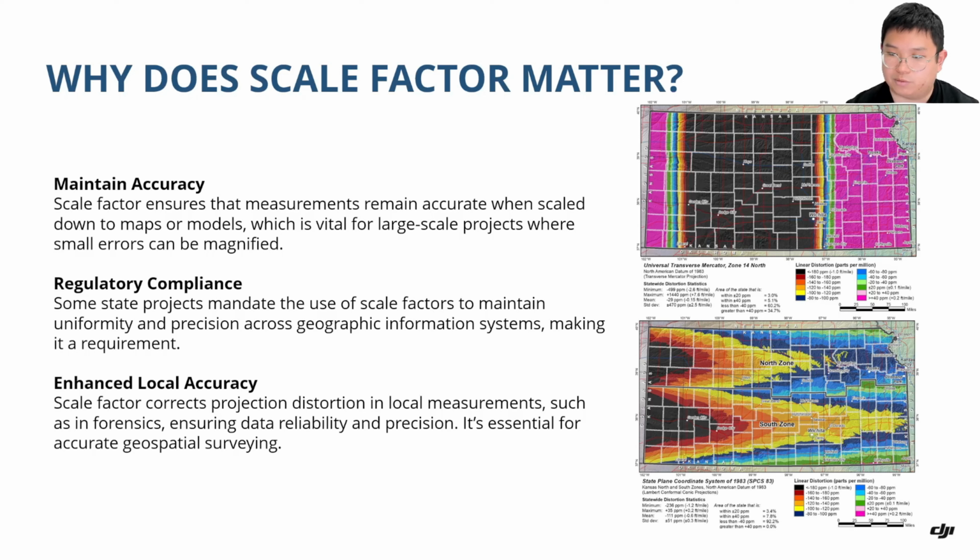On the right side, I have two maps which show the same Kansas state, but under different projection. As you can see, the linear distortion is completely different based on the type of the projection you work with. So knowing your projection first is important for you to apply the correct scale factor in your project.